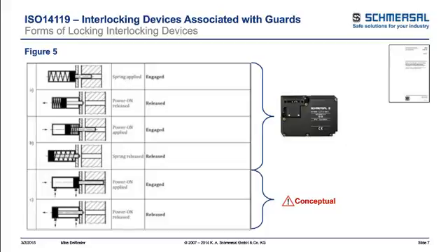But what is true is you really have to determine by your risk assessment what is the better condition. If you have a serious hazard potential with loss of power that allows that unlock to occur, that somebody can get into, and that's a foreseeable, reasonable type of hazard, then you may want to go to the power to unlock type of scenario just to accommodate for loss of power in that particular situation. But your risk assessment is really what's going to help you determine that.